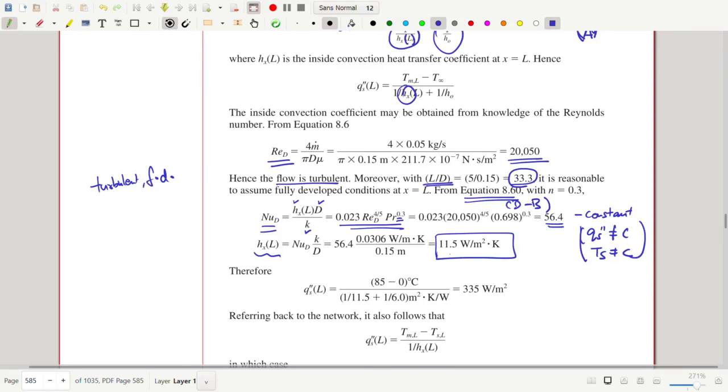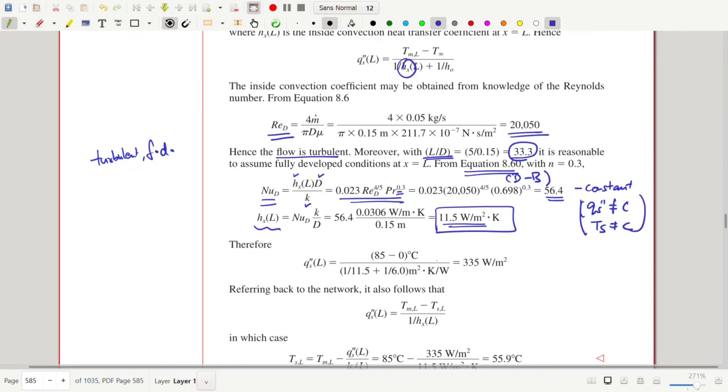This duct is not used for heat exchange. It is simply used for transporting this hot fluid. That is the reason you see that this value is not very large. And you can insulate the duct further if you want to reduce this value.